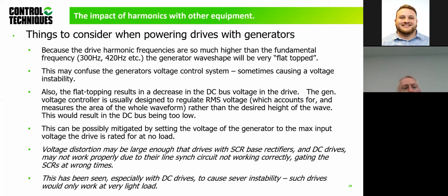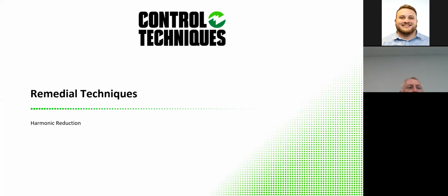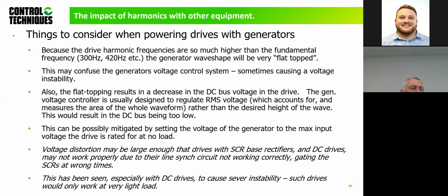Okay, now voltage distortion on SCR-based drives, I said I wasn't going to talk about this, DC drives, etc. You could have some challenges, okay, because the notching effects and the synchronization could have some problems. And again, especially with DC drives with very light loads, it can be instability. So I just put some little extra notes in there just as a guideline for some of these things when considering generators.